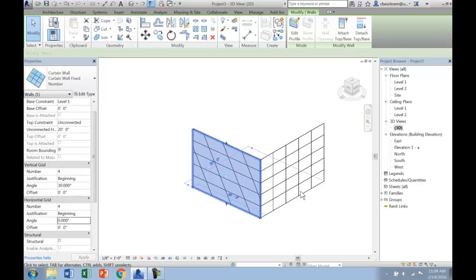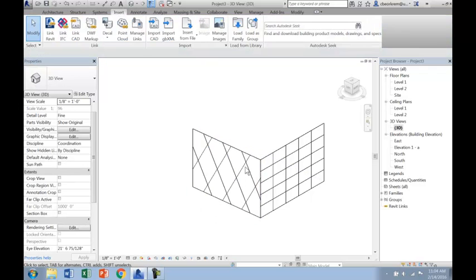I can turn the angle of say just the verticals, or say the verticals and the horizontals, to make more of a diagrid kind of shape across the surface. So it's one way to start playing with that. We're going to look at other ways to do diagrids with bigger elements and across the larger curtain wall systems. But certainly one way to start controlling the grid with more specificity.